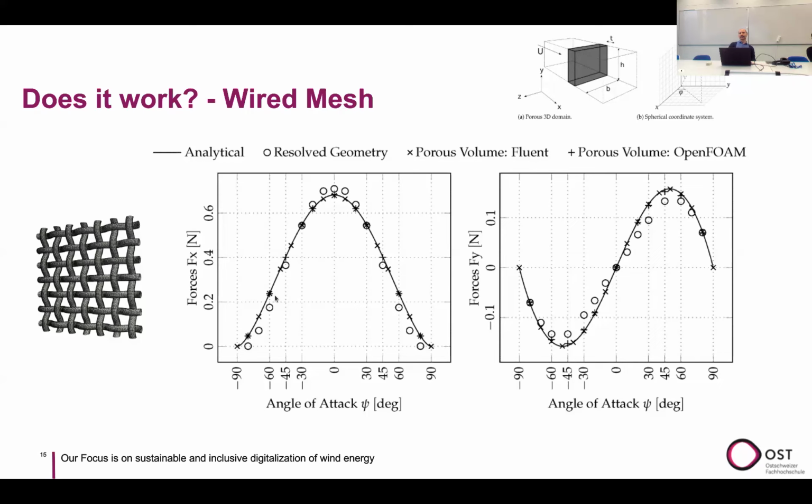So the good thing is that the computational fluid dynamics software solution, even though it's a finite volume solution, is very close to the analytical solution that we found from the equation that I showed before. And the behavior itself was captured. So we captured not only the forces in the X direction, but also the forces in Y.